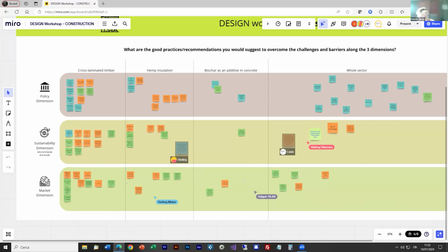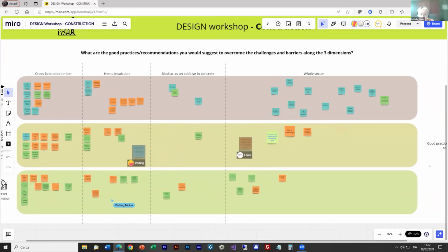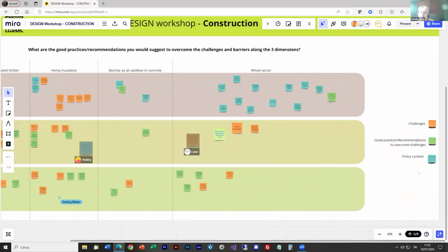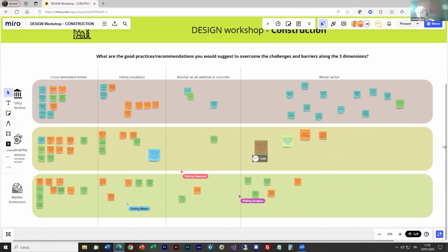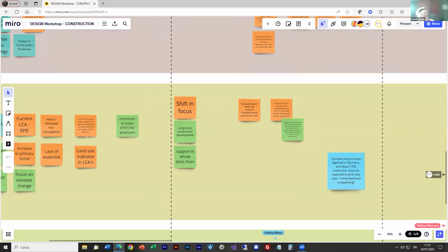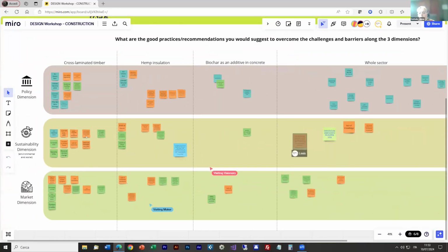So it's quite interesting. I wanted to add as well that there is now large research about the quality of glue, and on bio-based glue. So I guess that in a few years, very quickly, I hope, we will get structural glue able to be used in CLT. And regarding Stabilam, we also make nail CLT, in which there is no glue. We have also innovated a CLT in which the nails are also in wood. So that material is 100% wood, and it's very easy to recycle. The point is that economically it's more expensive than glue CLT, so it has a little bit less success.